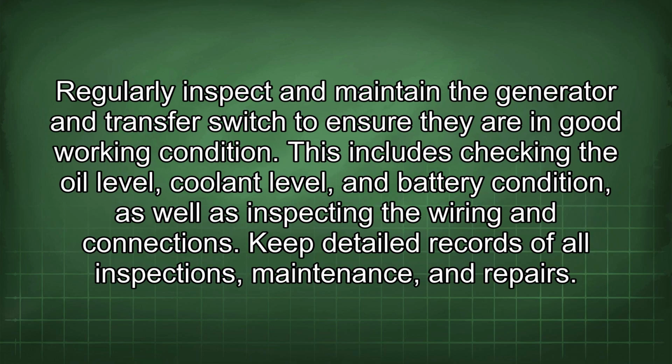Regularly inspect and maintain the generator and transfer switch to ensure they are in good working condition. This includes checking the oil level, coolant level, and battery condition, as well as inspecting the wiring and connections. Keep detailed records of all inspections, maintenance, and repairs.